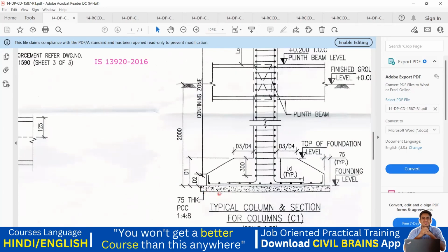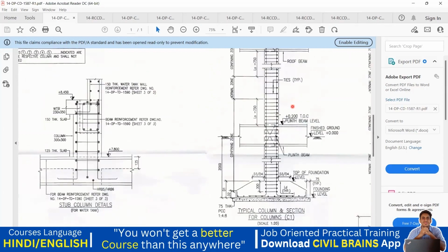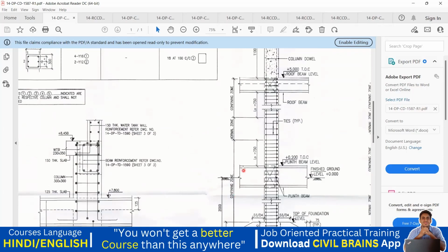Yeah, see, you have a PCC, then this was your D1, this was your D2. Okay, and then you see from here to here, this is D3 or D4, both are mentioned, since you're seeing it from the front side. Actually, back side also there is. In this side we have, but since it's a front, that is why they have mentioned D3 and D4. It's nothing but the offset from the column to the outer of this particular footing. And then next you are going to get the plinth beam, and then you are going to get the column. Now this is your floor to floor height. What is a floor to floor height? From here to here, it is my floor to floor height. From here to here, it is my floor to floor height.